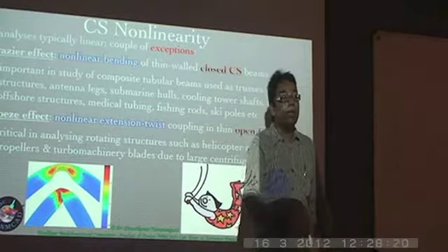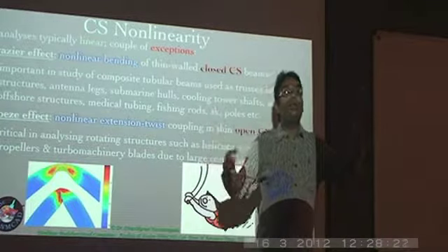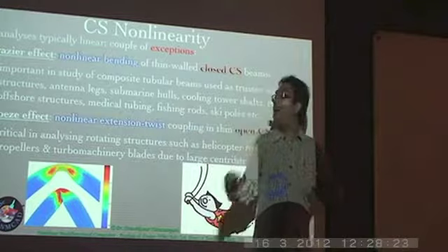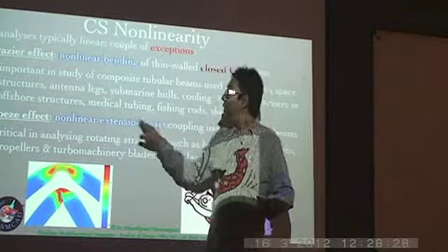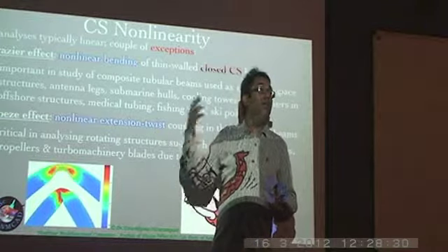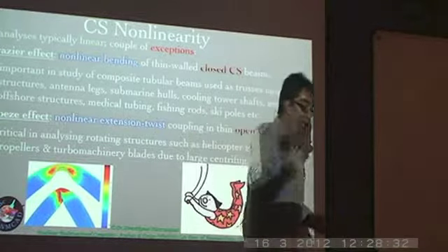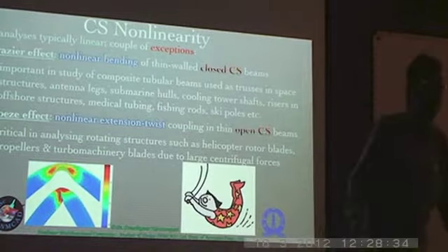But as far as the main rotor is concerned, all of the control actually happens through twisting the blade, and you already have the centrifugal force causing the extension. So this particular coupling that is there becomes extremely significant, and it's the same with propeller blades as well.